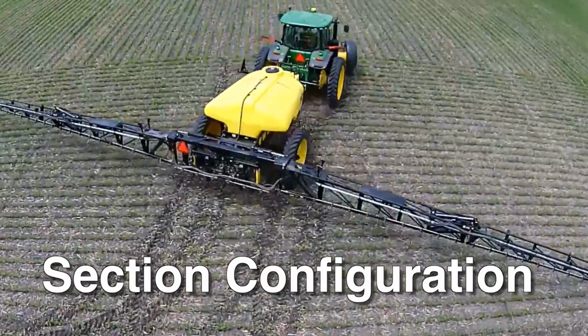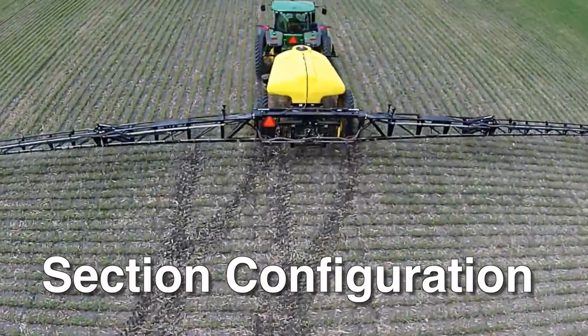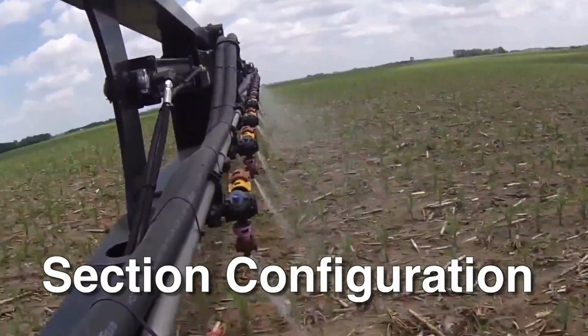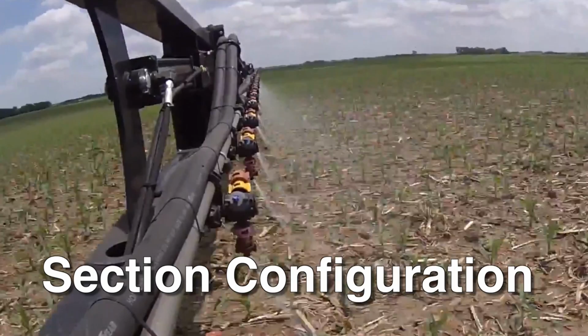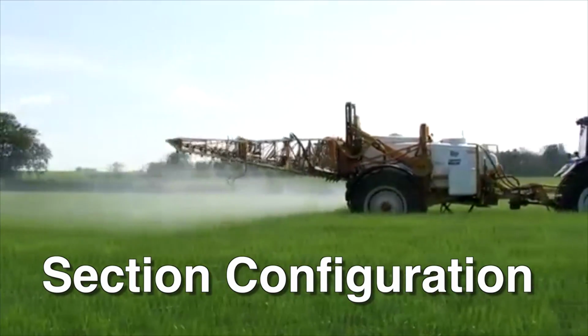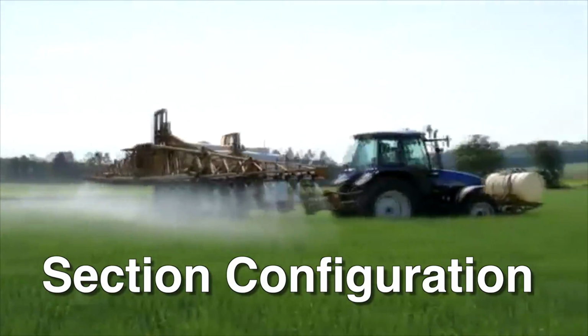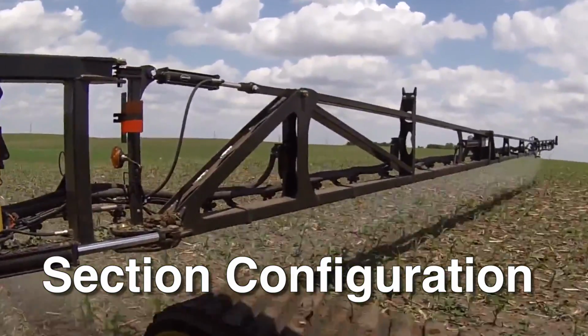Let's now configure sections. A section refers to a part of the implement in which all of the nozzles are supplied with product from a section valve. Closing the section valve switches off the section. The implement has as many sections as it has section valves which can be switched off. The first section is always on the left in the direction of travel, the second on its right.